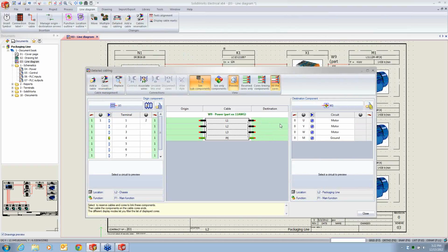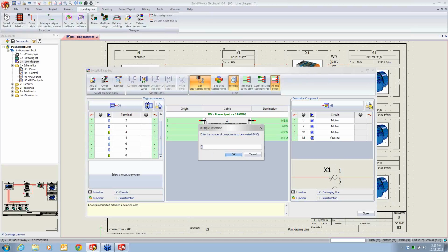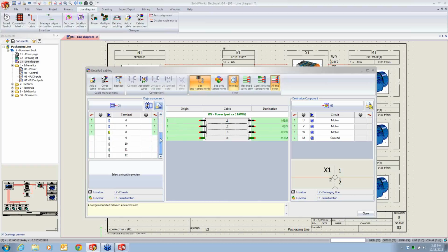And in addition to that, I actually can link this up into the different areas. So if you see here, I can just select on the different connection points here, and I can connect those cables in, and the information is automatically updated into the system. I can add additional terminals if I need some for my terminal strips. So in this case, since I have 4 new wires, I'm going to need to add 4 new terminals. And again, I just select these things, and I connect this information up.